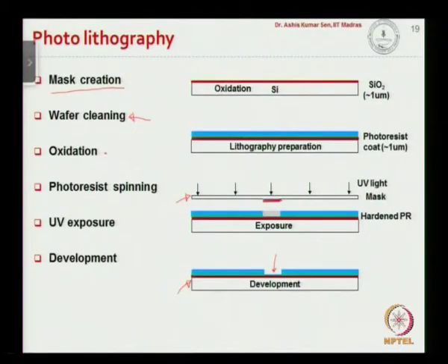And in some cases we use silicon dioxide as an adhesion layer between the substrate and the photoresist. So photoresist will stick much better to the silicon dioxide layer as compared to the bare silicon. So that is why we need to oxidize the wafer.